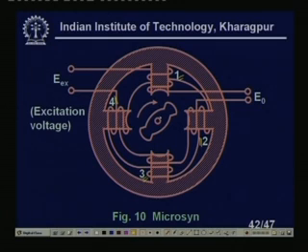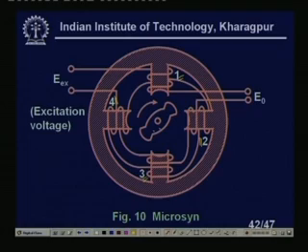If it moves, I will get an unbalanced voltage, right. That is the typical beauty of this synchro, this microsyn. You can see here, I have taken a section, there is no winding on the rotor of this microsyn, right.